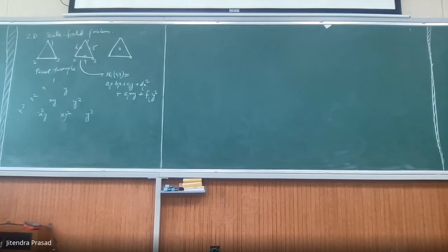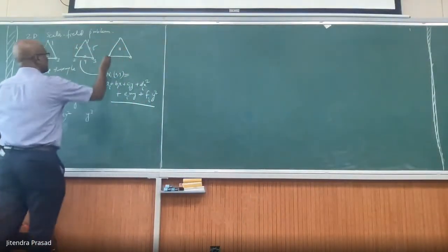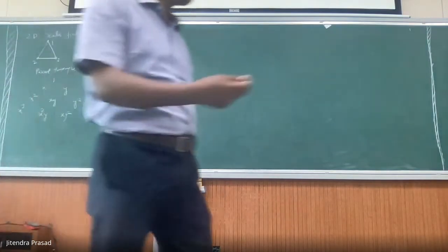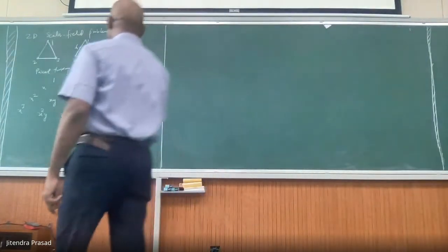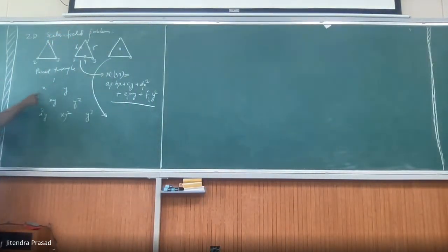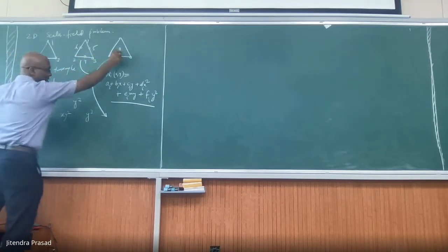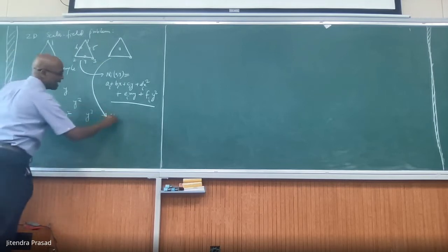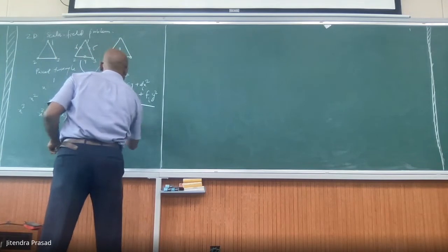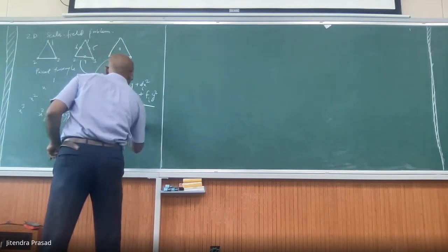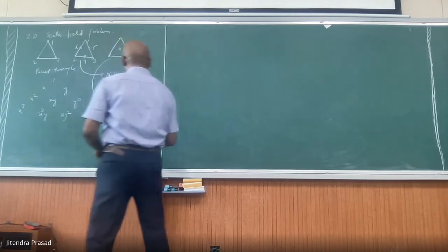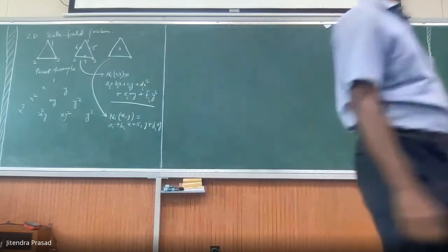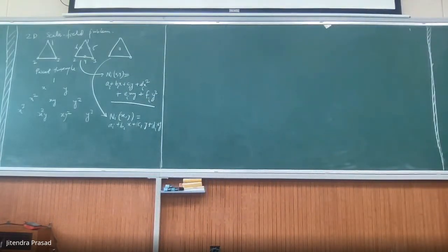Any question? Okay, so for this one it is very simple. Similarly, if you have some element like that, you can compose your own type. So it's possible that you have that, and in that case, can you write 1, x, y, and x square? Then it's not symmetric, and you see that being at the middle, it is more symmetric. Hence, you will choose 1, x, y, xy. So you will write Ni of x, y as Ai plus Bix plus Ciy plus Dixy. Of course, then you have to find out the coefficients from those equations. But this is the idea.